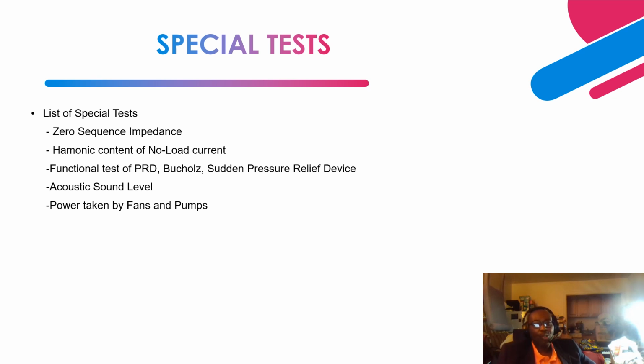So testing has to be done. Testing is done on no load, and testing is done with load. The sound level is measured at different corners and at different heights to determine whether the total acoustic sound level meets the criteria specified by the customer.